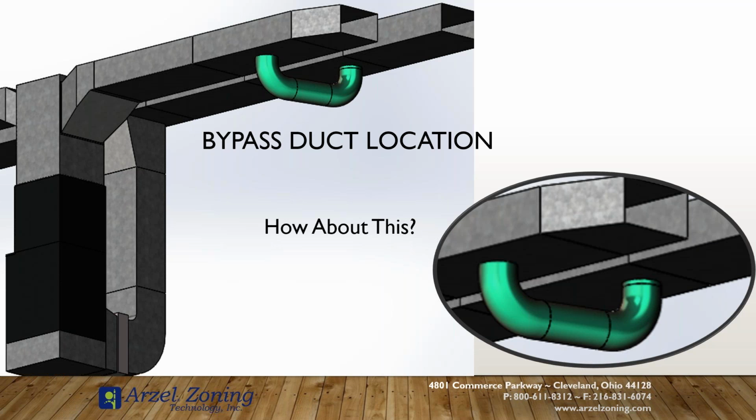So we're giving it a chance to deliver that capacity to the home before we start to dump it through the bypass, and then we're giving it a chance to temper itself before it's drawn back through the furnace directly. So that's why it's really best to have that bypass duct about 8 feet away from the equipment whenever possible, but before your first reducing adapter, preferably.